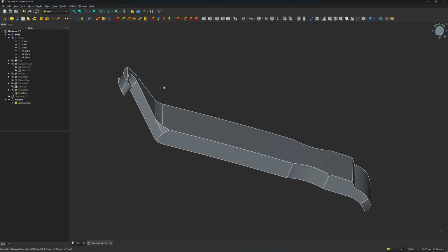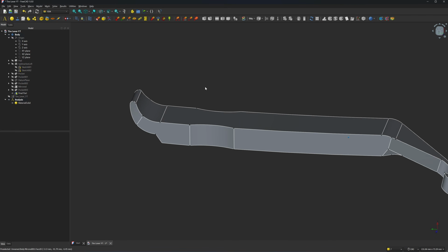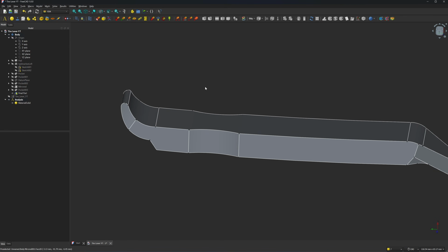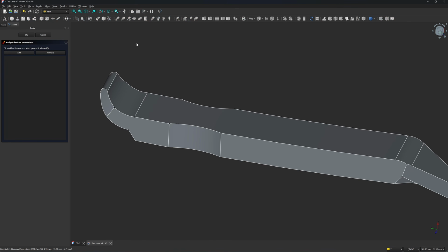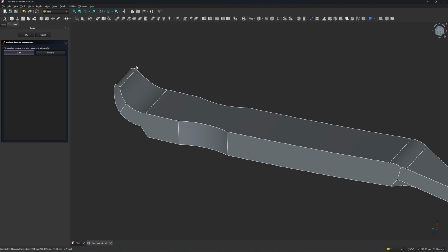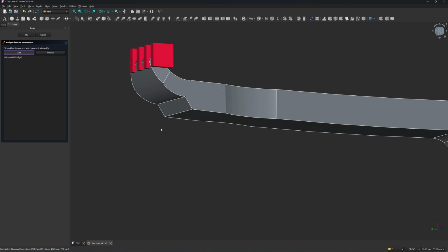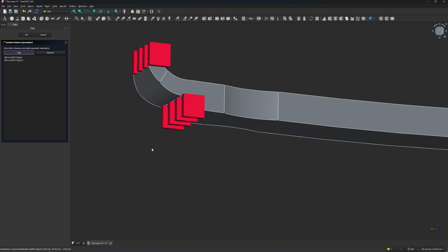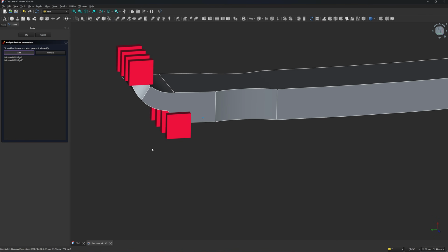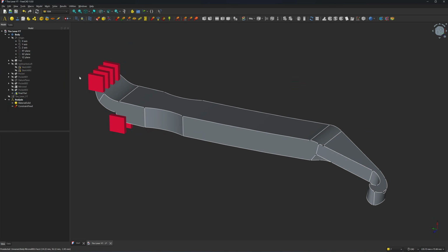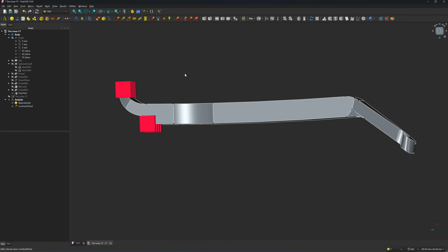Next, I'm going to create a constraint. To do the physics simulation, you need materials, and then you need a constraint. To add a constraint, I click on this fixed boundary condition, and then I'm going to click on add. I'm going to select this edge here. This edge is going into the tire. When you remove the tire with this lever, it's going into the inner tube, this part. Click it here, and this part will be resting on the rim. So I'm going to click it here. I click on the edge because I want it to be able to rotate freely on its axis, right? Next, I'm going to click on OK. So now we have materials and a fixing point, the constraint.